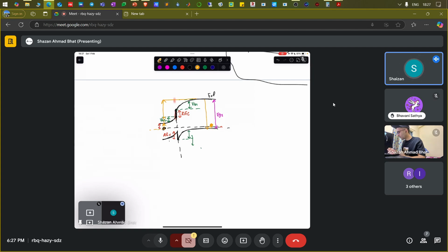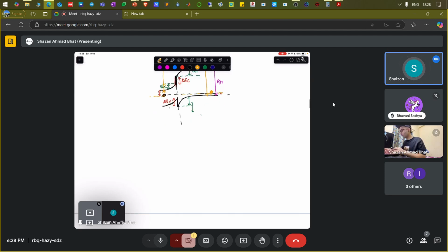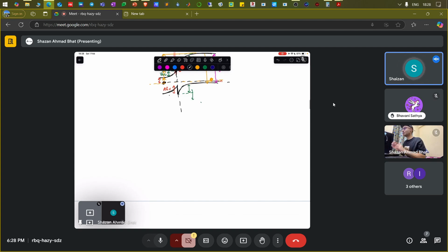This is the line you choose, and it forms a closed loop. If you sum over all of the voltages you have encountered in between, you are going to compute the overall built-in potential. But you always have to form a closed loop, otherwise it is going to create a problem. That is also one of the problems in your assignment.